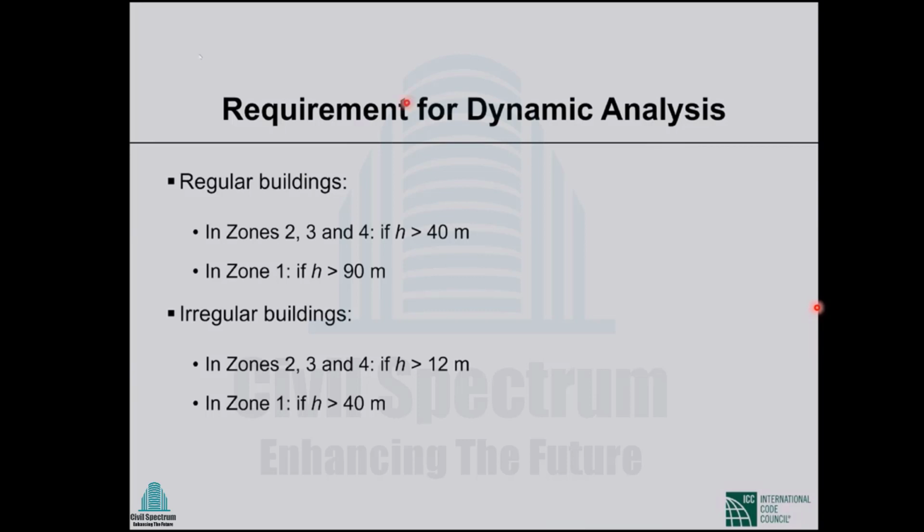Now, another important thing is the method of analysis. For earthquake loading, what method of analysis can we adopt? We are used to applying the equivalent static load method, but this time, and in the previous code also, there were restrictions, but this time the restrictions are much stricter.